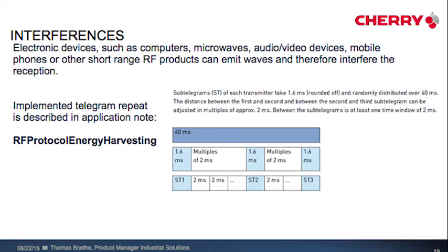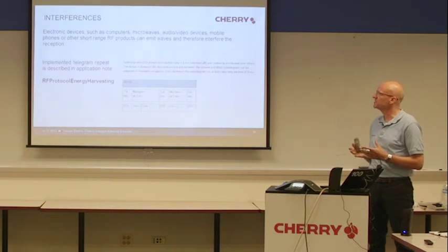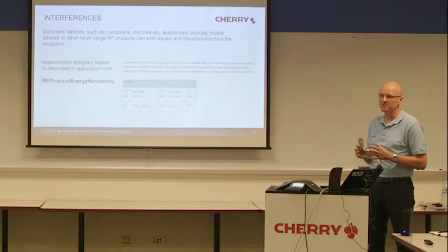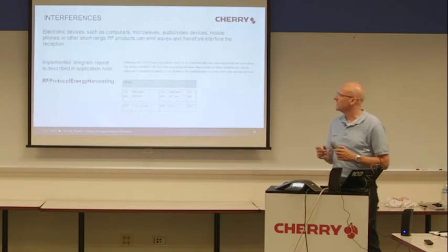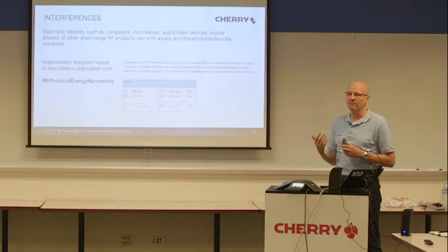But you can never cover all environments and all circumstances of a real application. What we implemented in our RF system against interference from other systems sending on the same frequency is the repeating of our subtelegrams.